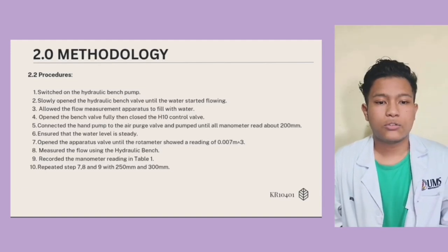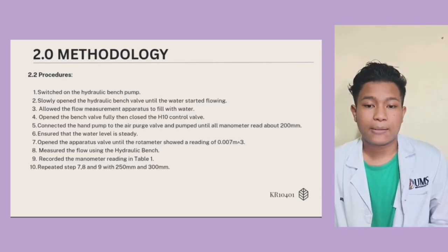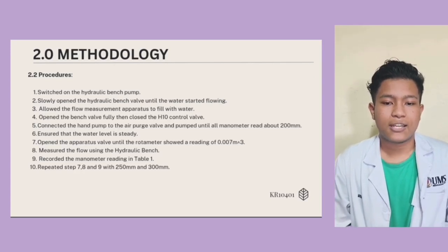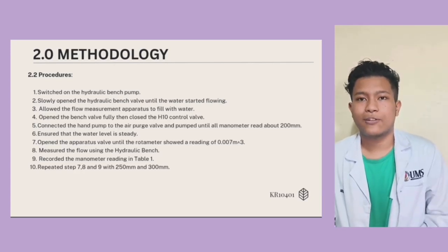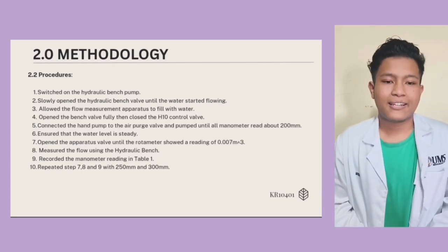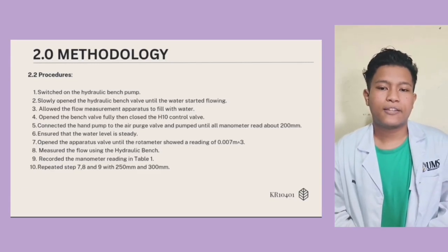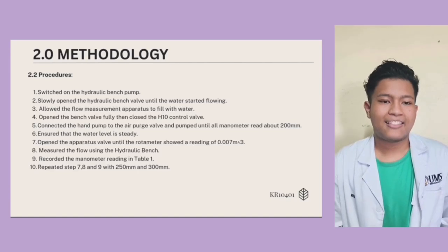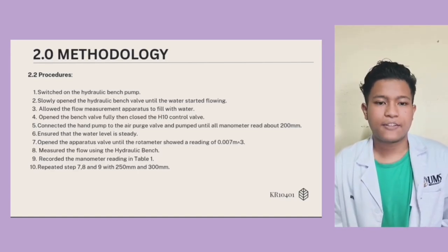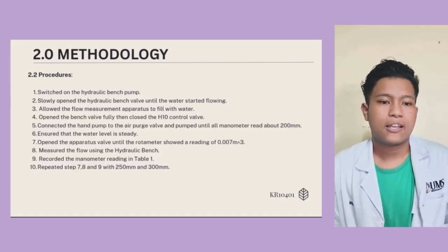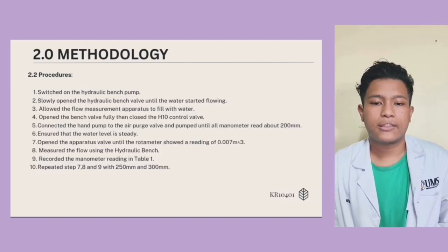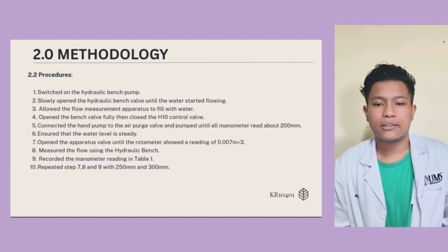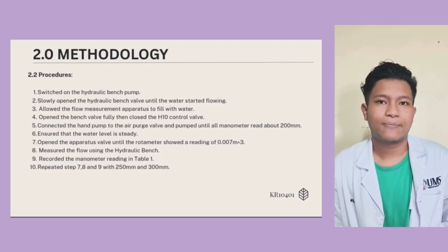The ruler was used here to record the distance between each tapping point along the conduit, which allows us to plot pressure head and velocity head against distance accurately. This entire process was repeated for three different diffusional heads: 200 mm, 250 mm, and 300 mm, giving a range of data sets to analyze. These readings were crucial in calculating the static head and velocity head at different sections of the tube, which helped us understand how energy transforms throughout the system.